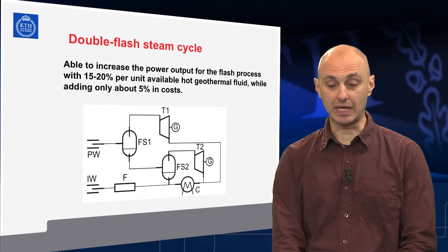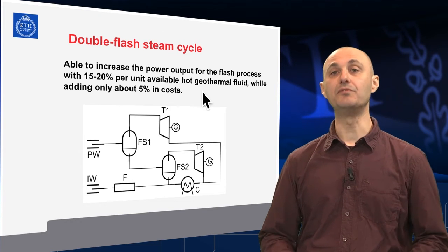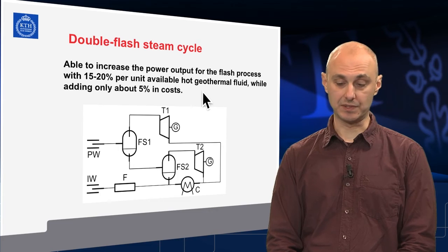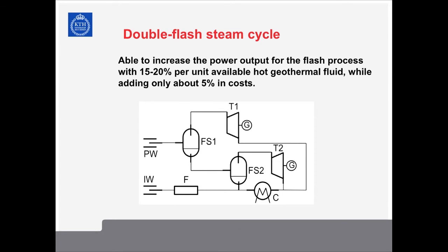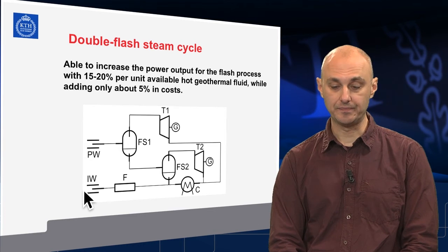The double flash steam cycles are simply trying to improve a bit more on the single flash process. They rely on the same hydrothermal resources at the same starting temperature and pressure, simply applying 2 steps of a flashing process instead of only 1. There are 2 flash chambers, the second one drawing the liquid remainder from the first flash process and flashing it again to a much lower pressure. All of the flows are mixed in the end and pumped back as liquid to the injection well.